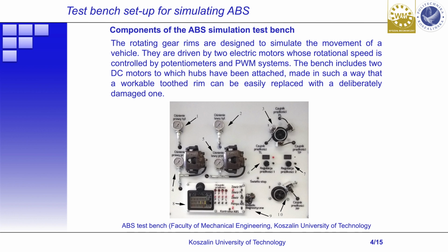In addition, tests can be carried out to determine whether the ABS system is triggered in the event of damage to the toothed rim or if the distance between the sensor and the toothed rim has shifted.